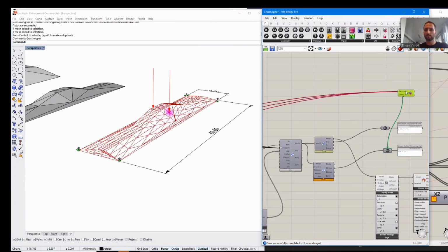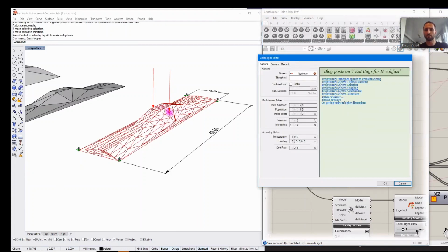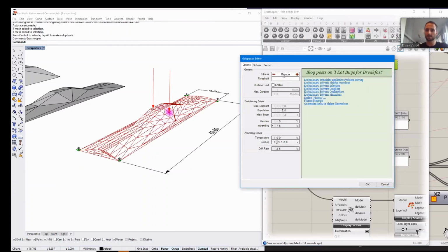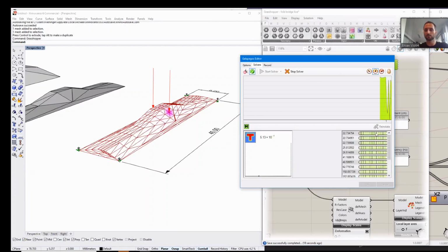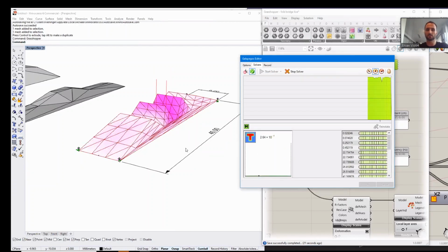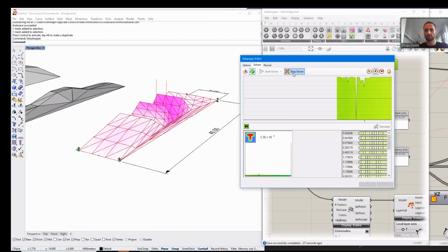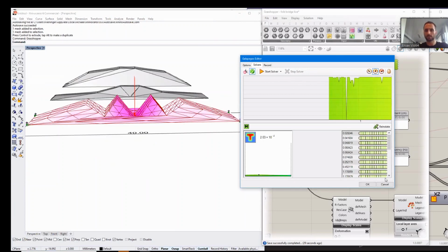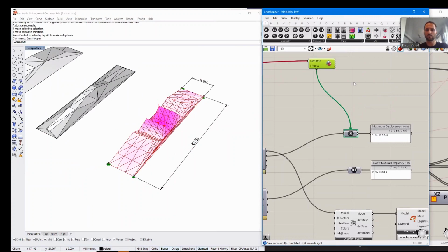All right, and we could just take this maximum displacement value and optimize with Galapagos again, this single objective, changing the fitness goal to minimize in this case, and start the solver again, and it will again solve for this one optimization goal. See a number of funny global tryouts already here. But looking at the time, I will just jump straight into the multi-objective setting now.